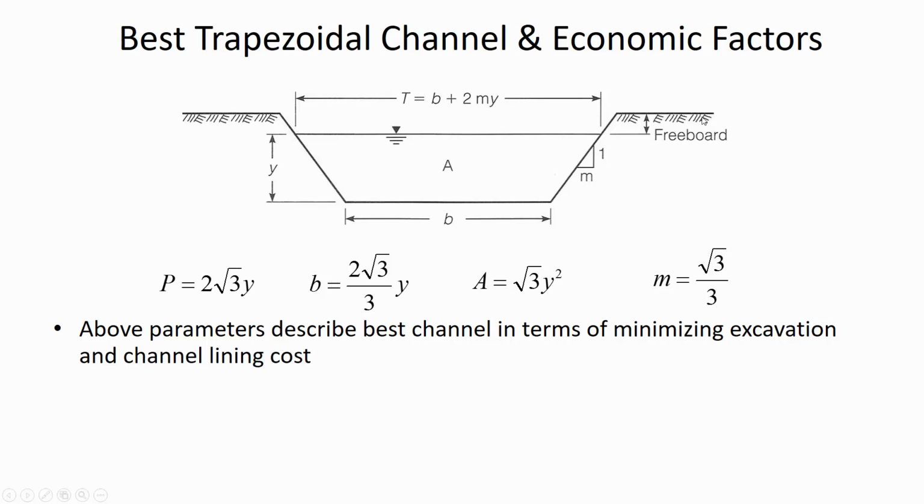I want to point out one other note on this drawing, and that is freeboard. And we'll talk about channel design and how you have to calculate freeboard in a minute, but you would want to provide a little overhead, a little extra flow capacity in a trapezoidal channel, because for one thing, you might have more flow than you originally expected, but then on top of that, this additional freeboard gives your channel capacity for any wind-driven waves. Like if you've got a windy day and it was all the way to the top, then the water could spill out of the channel simply because it's a windy day, or splashing, or waves that are related to maybe a hydraulic jump upstream or downstream.